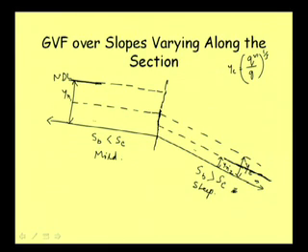Similarly, when we talk about the upstream flow, upstream of this section, this is subcritical. This flow is subcritical because the depth is more than critical depth, and as it is subcritical it will be influenced by the control at downstream at this point. So, the downstream being supercritical will be controlled by this particular section, and upstream being subcritical will be controlled by this too. So, this will influence both.